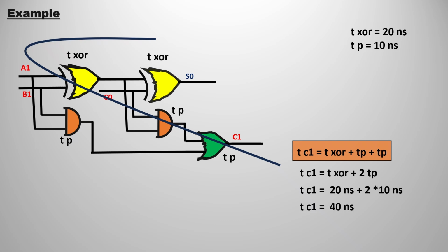As this is a single full adder, we are having 4 single full adders cascaded with each other. So let's observe the first full adder. This is the circuit diagram of the first full adder. First we are going to obtain the full adder's propagation delay of the carry. If you observe how the carry is obtained, you first have to pass through the XOR gate, then the AND gate and the OR gate. This is the way we pass to get the final output of carry.